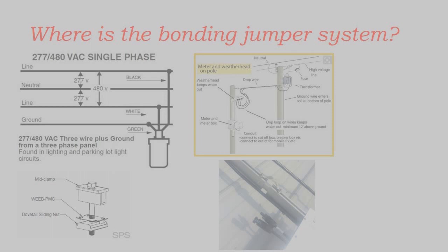And so what we see down in the middle lower picture is a grounding washer between two pieces of rail. Now there's a stick of metal right smack dab in the middle of these two pieces of rail, and that piece of metal is there to splice the rails together and turn them into one rigid piece of rail instead of two separate pieces.